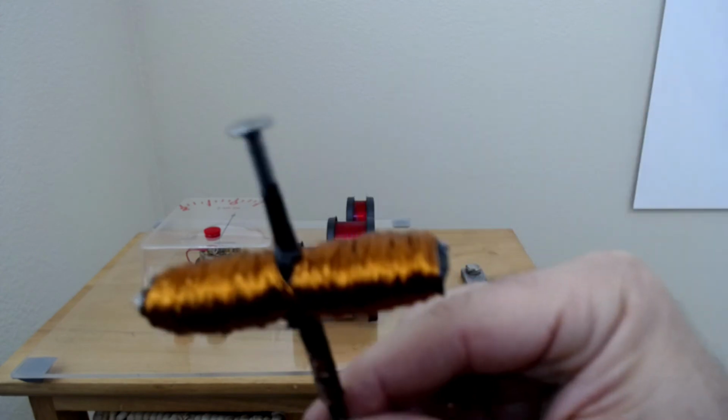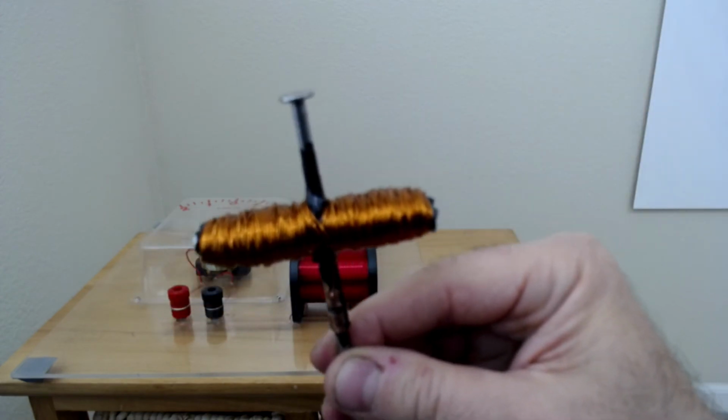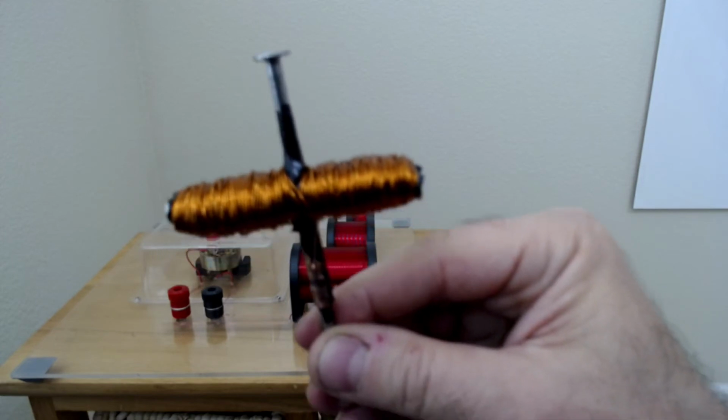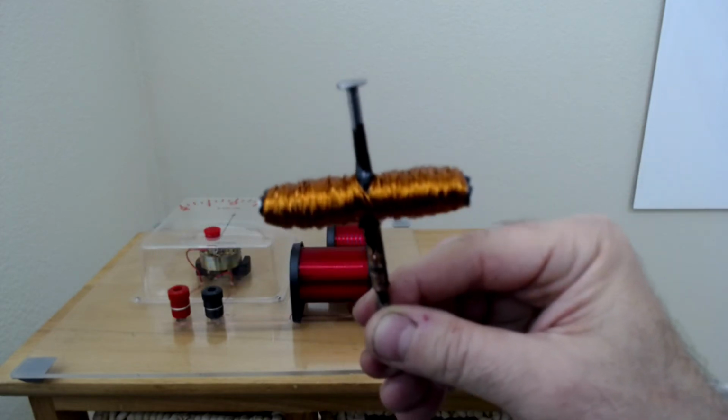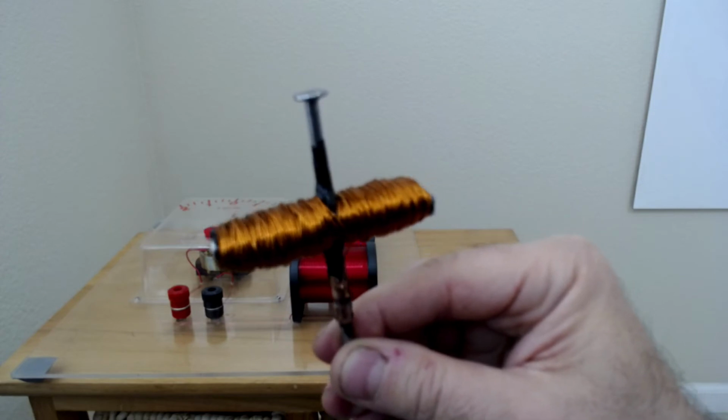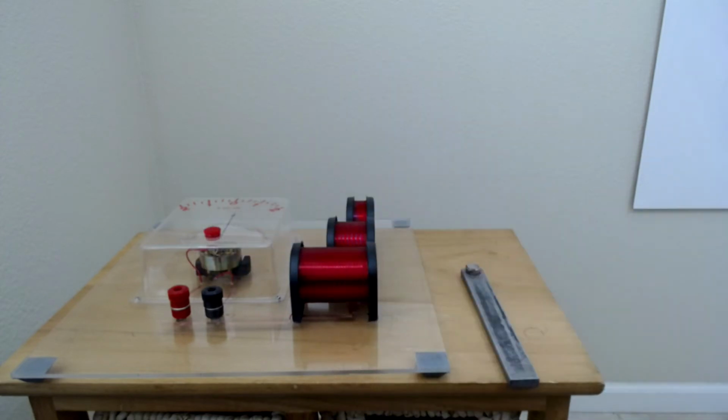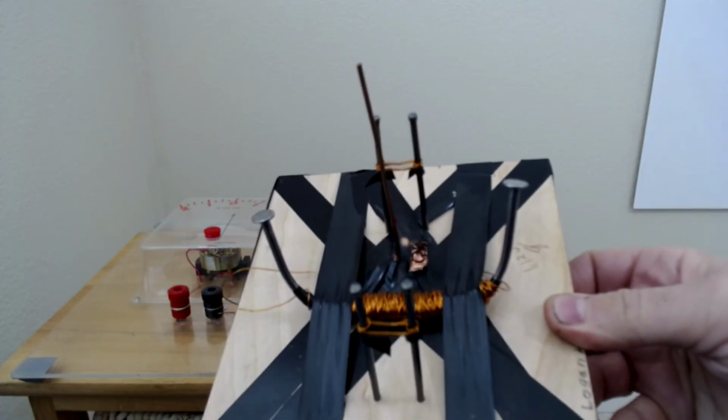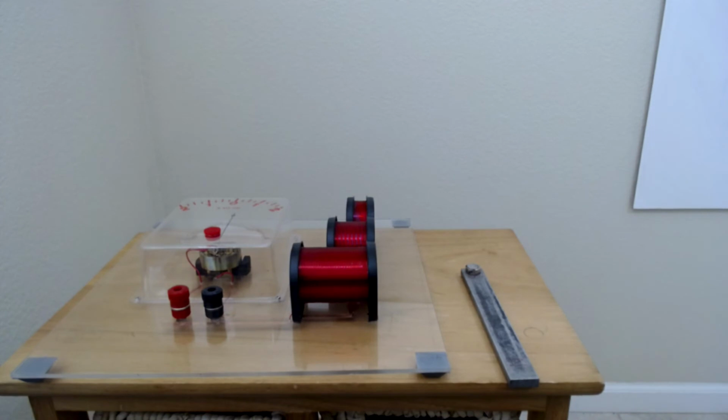It's very important though when you wrap the armature that you minimize its moment of inertia. You want nice symmetry and a nice, tight wrapping. This one was good enough that it ran at 1.12 volts. Sometimes you just get a big ball of wrapped wire and that's not going to work very well. So building is not going to be too bad. Oh yeah, by the way, you're going to need a hammer to nail things into the board. But most of the issues are going to be troubleshooting.